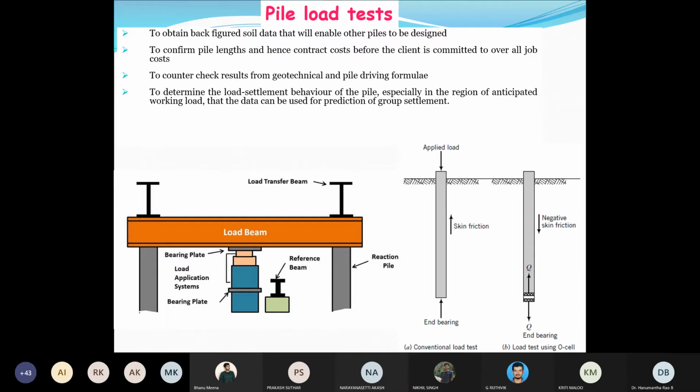So this is one of the primary reasons. Though we have calculated the ultimate capacity of a foundation system, we curtail it to allowable pile load capacity or footing load capacity. When we say allowable, this strictly keeps in mind the allowable settlement, so that no excess load goes onto the soil or the pile material and they do not undergo failure.